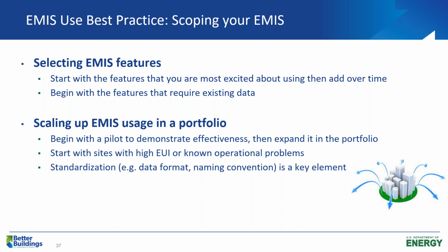Scaling up within a portfolio. These are generally important in energy efficiency. You might want to begin with a pilot to demonstrate effectiveness and then expand. We saw a lot of folks doing that. And then standardizing your process. Data standardization is something that the EMIS vendors will help you with, naming conventions and mapping points to their system. Those are all key issues in making sure that the EMIS is working well for you.